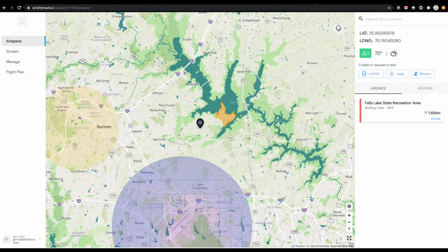we might be able to fly in what appears to be controlled airspace where LAANC might not be yet supported. We can document areas that we want to keep our pilots away from certain assets, or maybe want to highlight our training field where they're pre-approved to fly. And this can trickle down all the way to maybe land use agreements if we're flying on private property or something along those lines. So there's a lot of reasons that we could use it,